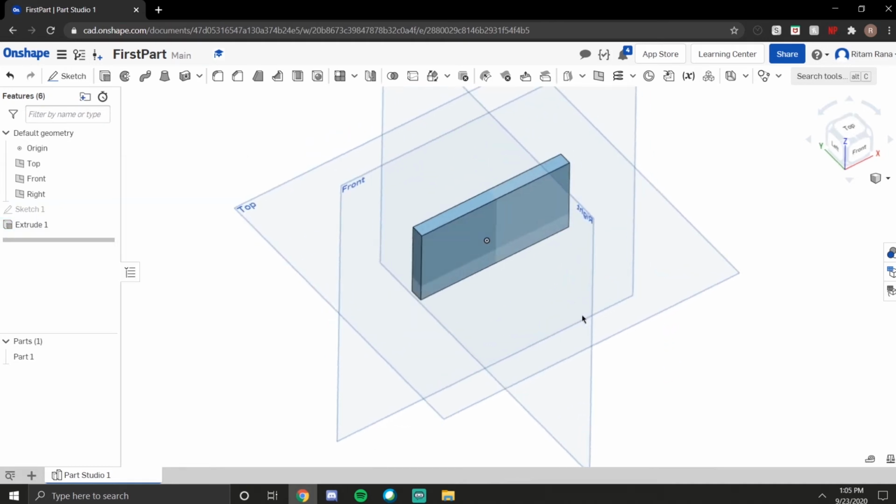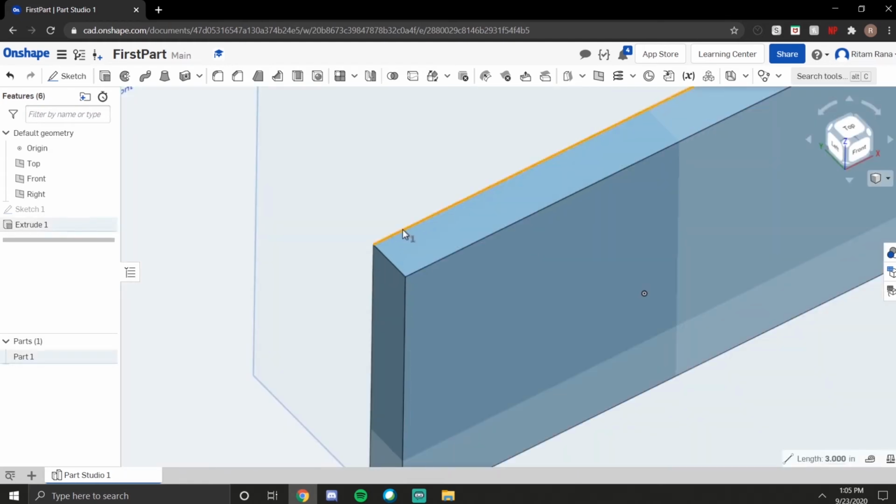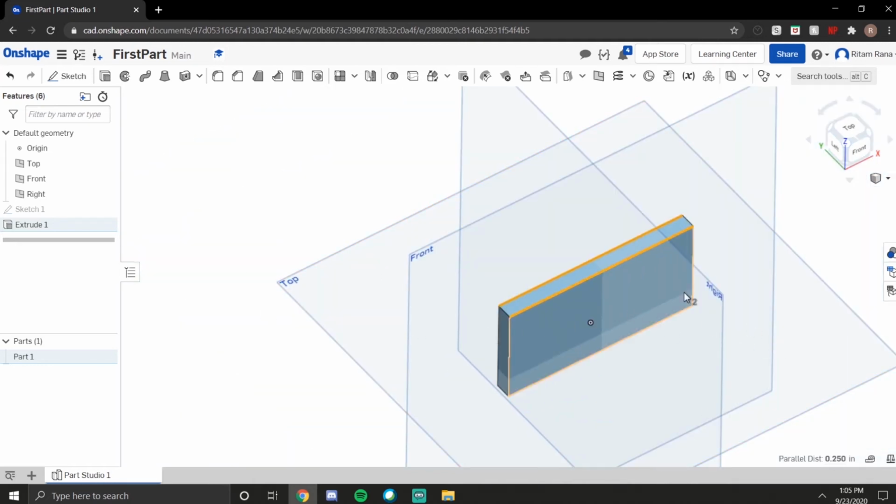So we can make sure it's 1/4 inch by clicking on this tool, clicking on this line to this line. So as you see in the bottom, it says 0.250, and this is a useful way to check dimensions. You can't really change this dimension, but it's a useful way to check the dimension. If you want to always go back and see how long you made it, how deep you've made it, etc. So we can click on the tape measure here, and it shows the measure details. So it'll tell you the X, Y, and Z coordinate, it'll tell you the minimum distance, the parallel distance, and the length. So the length of this point to this point is 6 inches.